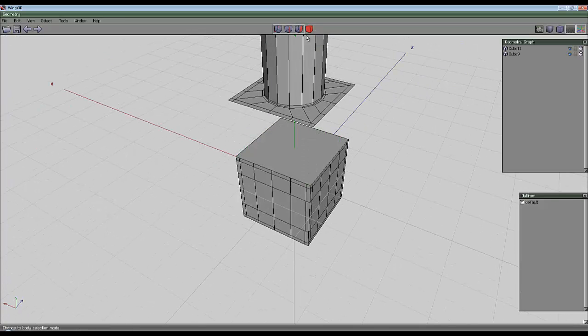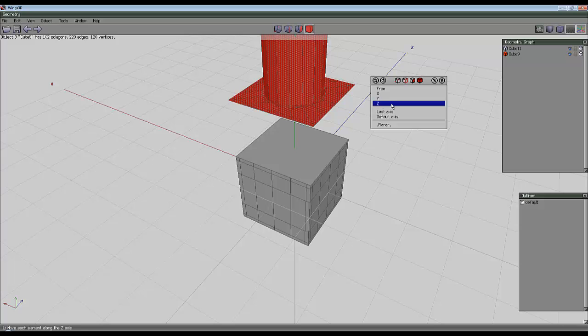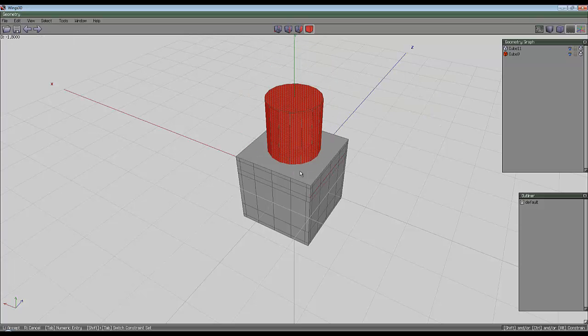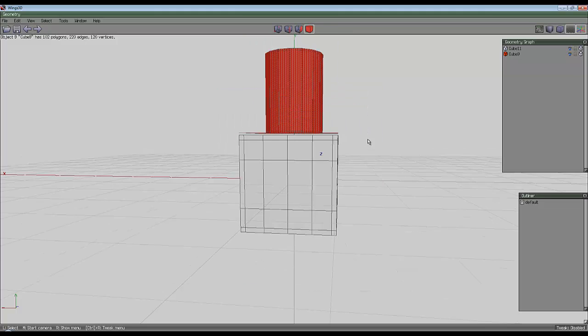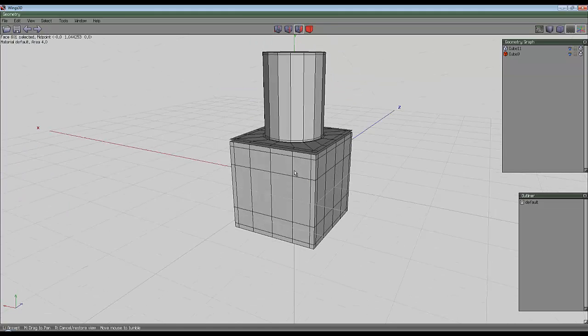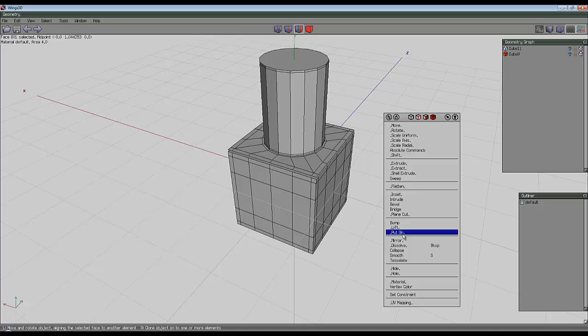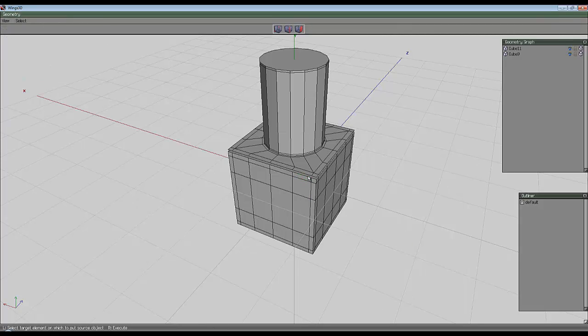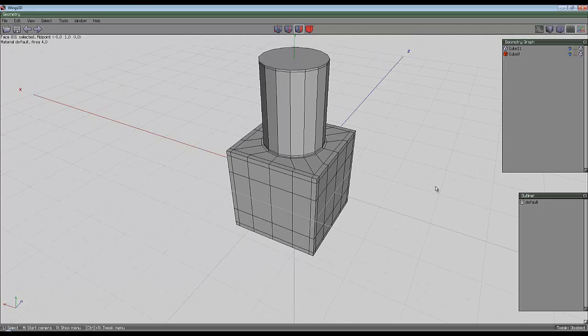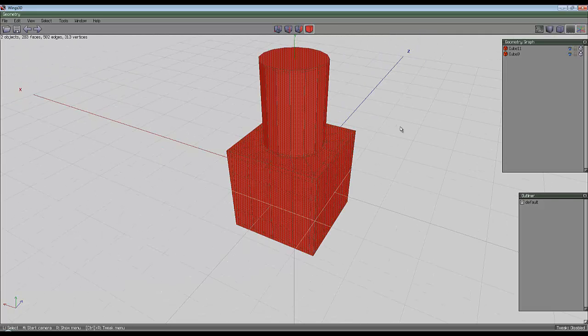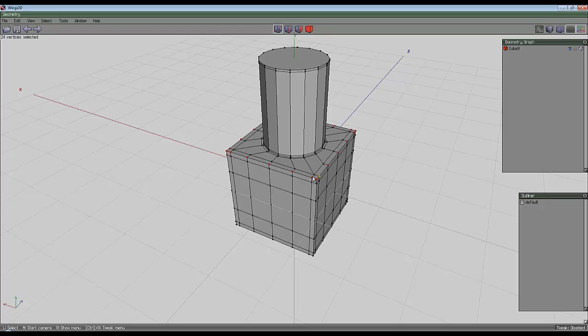I've deleted that, so I can now, if I move that down again, move it on the y-axis, I'll get it to line up exactly, which since I just moved it up an arbitrary amount it won't, so I'll have to use the put on command again. So right click and left click, I get in on that face there, and then right click to execute it, select these two objects and weld. You can see that it welds along these edges, so that's going to work.